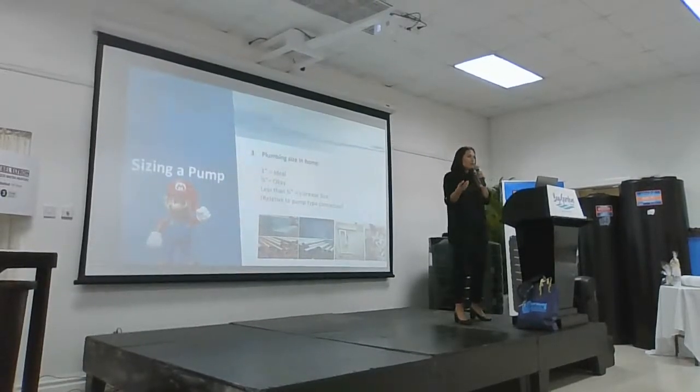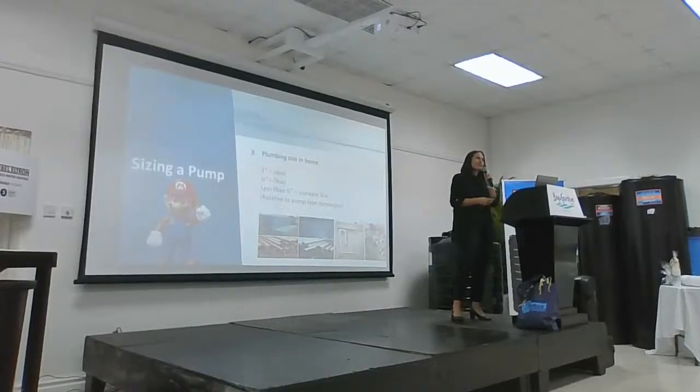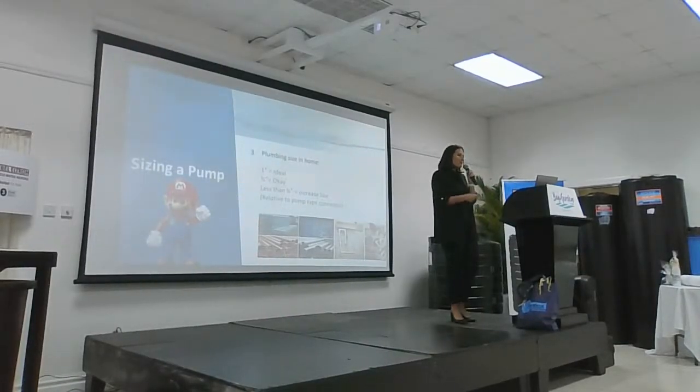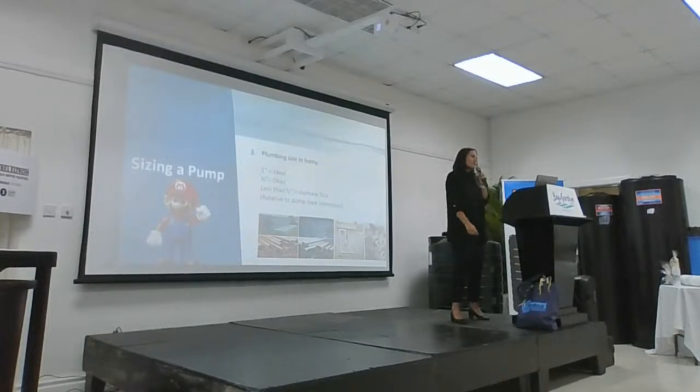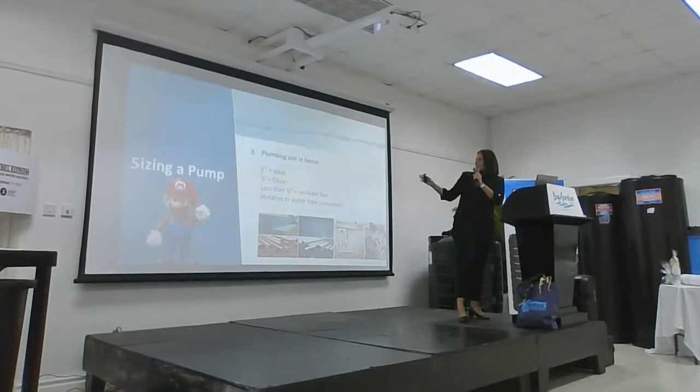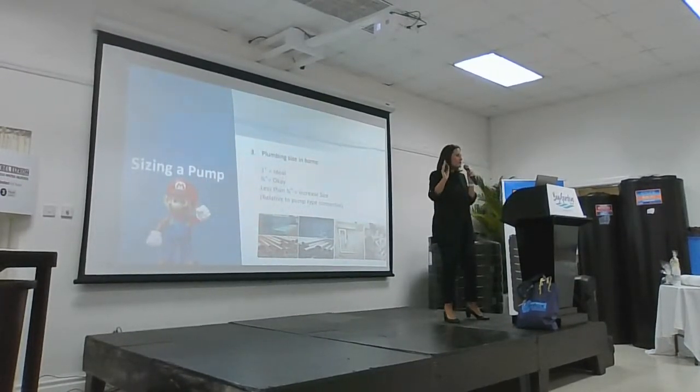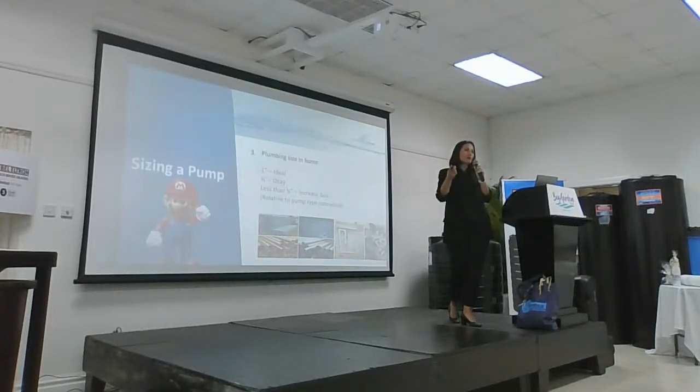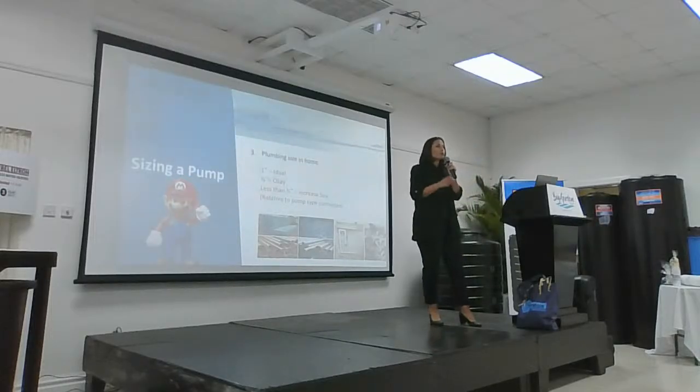I know that within the Caribbean, 1/2 inch pipes in homes and 3/4 are very, very common. So I would like to encourage you to say 3/4 is okay. But where you have 1/2 inch pipes, we actually recommend to size up in the horsepower, because your pump now has to work overtime to overcome the friction loss that it experiences in the pipe throughout the house.